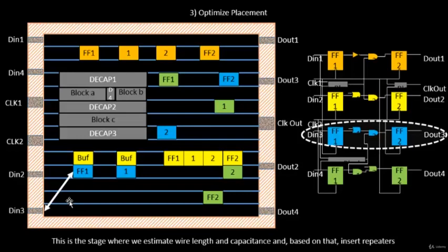Basically, once we move into timing analysis for ideal clocks, we'll talk about what the acceptable marginal condition is for the signal to be considered a real signal, or a sufficient signal to trigger flip-flop 1. We'll talk about that. So from Din 3 to flip-flop 1, we might not need any buffers. Flip-flop 1 to logic 1 also, we might not need any buffers, because this is a reasonable distance. From logic 1 to logic 2, we also might not need any buffers, because it looks like it will be able to send the signal faithfully to logic 2.